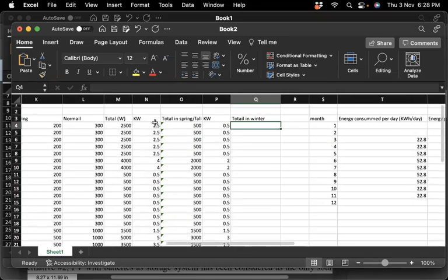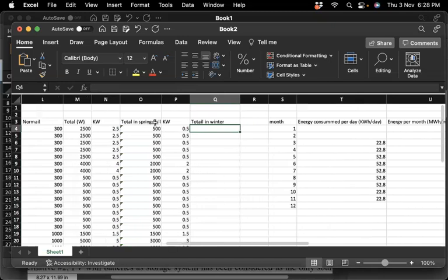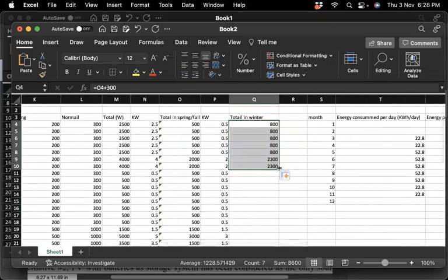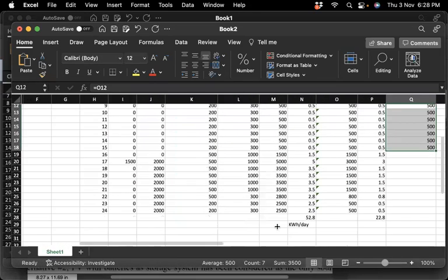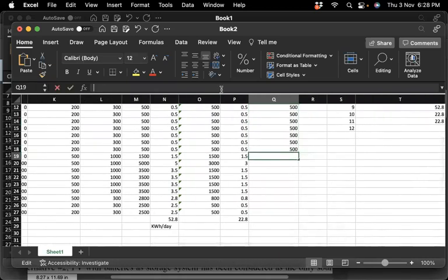So, for example, here during the night hours, our power is the same as in the spring plus this extra 300 watts representing extra lighting load, which will extend somehow till 7 or maybe 8. And then it's the same as the spring loads here during the morning, and then starting from 4 o'clock again, we have an early sunset in the winter, so we return to having an extra 300 watts for lighting or whatever. So this is typically what happens.